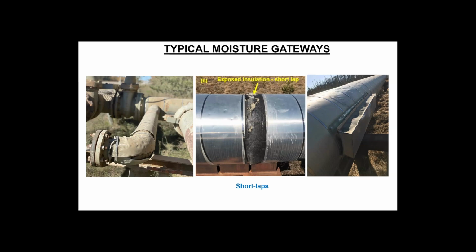The one in the middle, you can see that two ends of the jacketing are wide open. That happened due to the thermal expansion of the pipe. I would say in this case it could be the fault of inadequate specification, where the proper overlap was not maintained, or the thermal expansion was not accounted for. Due to the thermal expansion, the jacketing parted ways and opened the insulation. You can also see torn-up insulation that could be coming from ravens, crows, or birds biting on those pieces of insulation. So we could see some damage, and that's actually a moisture gateway.